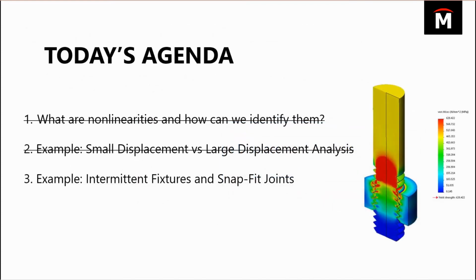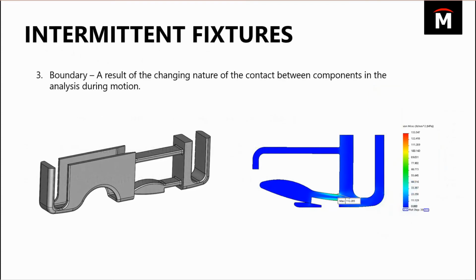So that's probably the most common nonlinearity I see, besides maybe someone knowing they have a nonlinear material model they need to run right off the bat. The next one I'd like to take a look at, though, is harder to identify. And this is that contact nonlinearity. Certainly I can pick it out quickly if we're talking about a custom complicated thread connection, or something that has sliding press fit or needs to permanently deform so that it yields beyond its permanent deformation point in the material curve. Those you can see pretty quick, but sometimes these contact conditions are not as easy to see.